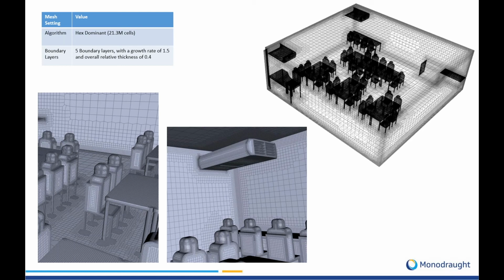Fantastic. We have another question about filters. Are there any filters in this unit, and is it possible to add bespoke filters in? Yes, we've got a filter within the X Plus system, just so that the gap between the water coil and the fan is an area where the maintenance is limited. So therefore, we've fitted a mesh filter there, so that for cleaning purposes, that part is accessible.